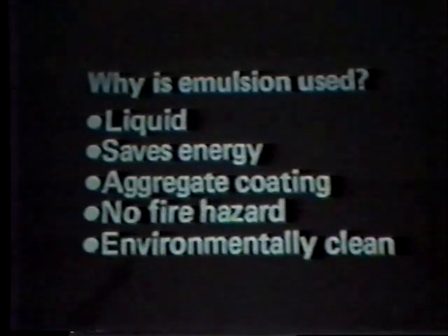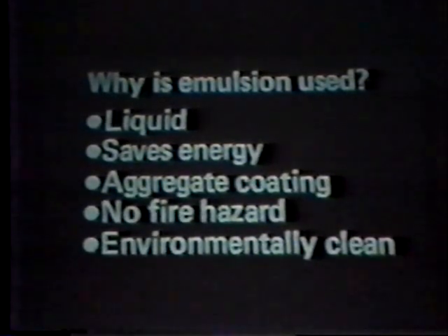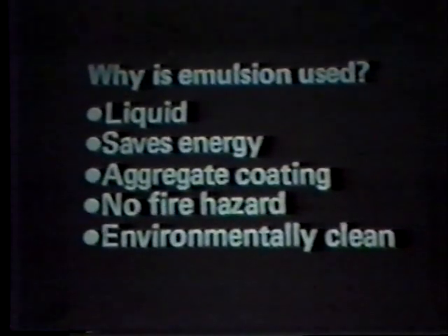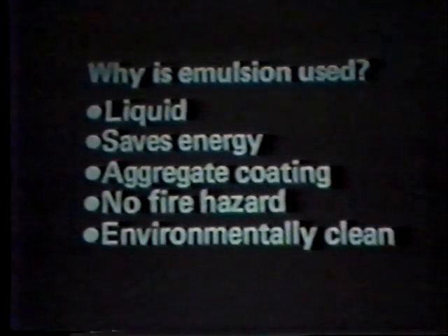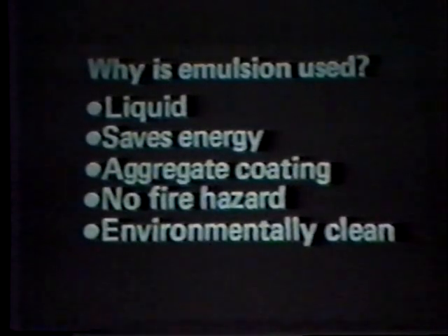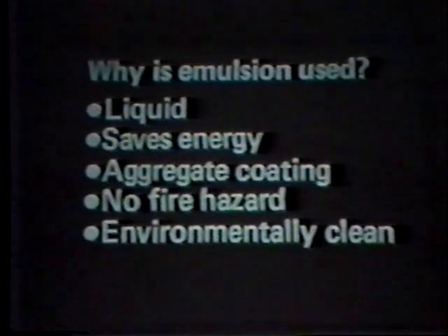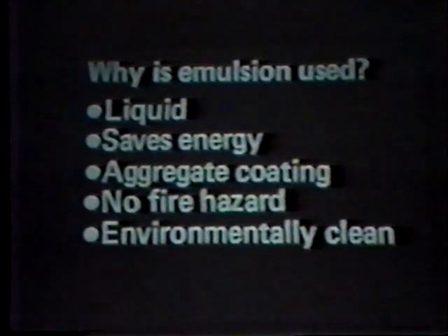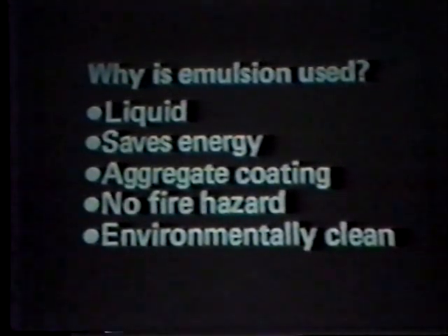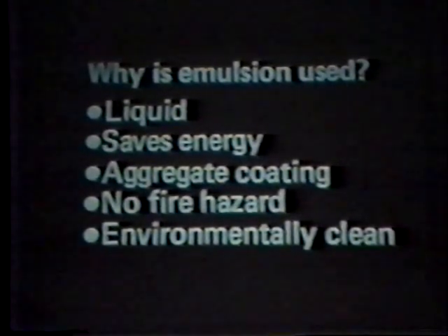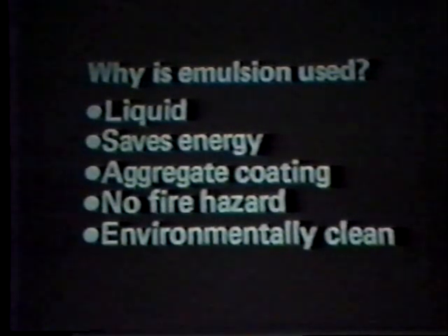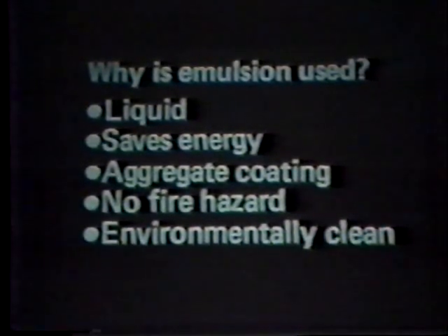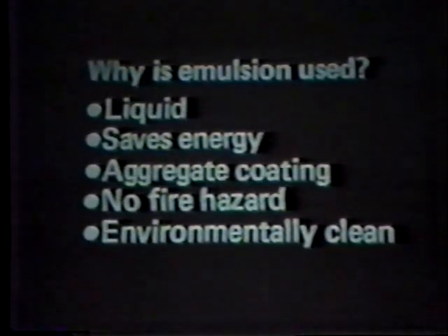The other is we believe we get better aggregate coating and can manage aggregate coating better with emulsions than we can with cutbacks. There's no fire hazard because in every case with an emulsion, you're working at well below the boiling point and never reach what we call the flash point, which you can reach with cutbacks. When you're using a product that has gasoline mixed in it and you're spraying it at about 300 degrees, believe me, you've got a good chance for fires, and there are some that have happened, and explosions. So emulsions are much safer to handle.